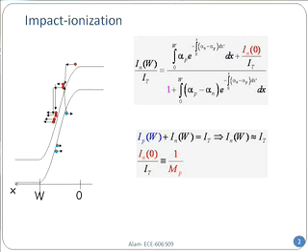And also, let me write this quantity: I_N of W as a fraction of I_T is some number, M_P. That could be a million. So that is the total current that is getting out at the point W relative to the current that was injected at the initial seed point. That's really what I am calling a global multiplication factor, M_P. So this number, by the time it is done, you may inject one electron and you can get 10,000 out from the W point. So that's what this number is, a very large number.